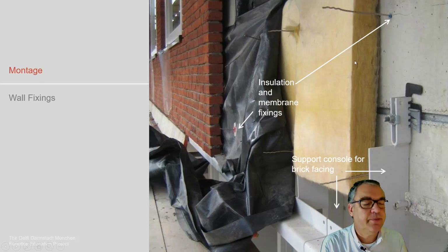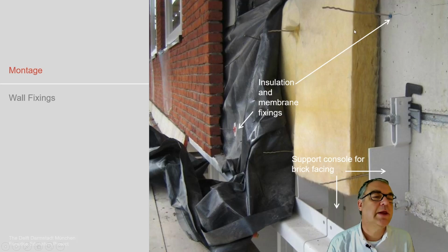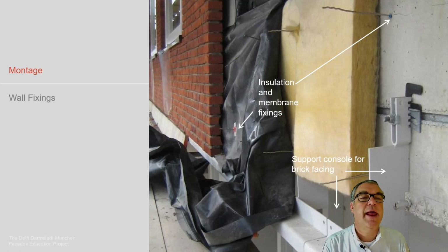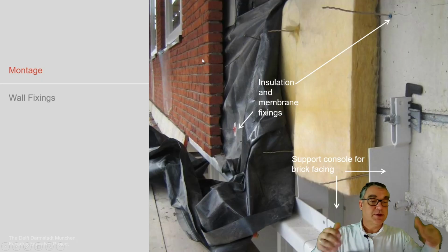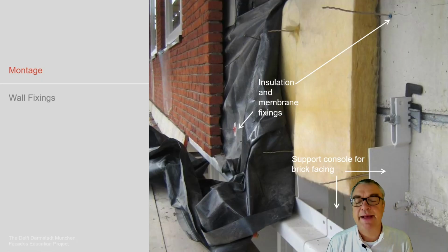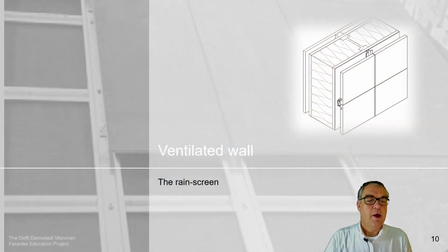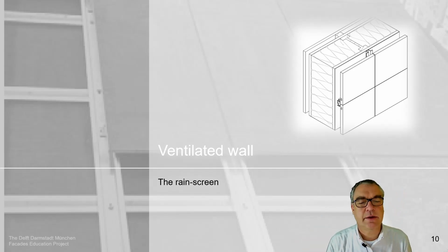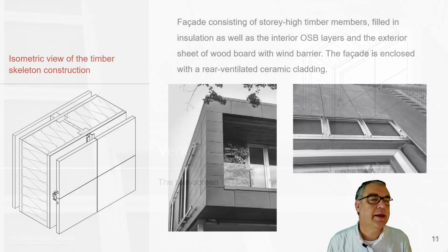We see the insulation, we see the fixing devices, the rods brought into the concrete directly, keeping the insulation in position, penetrating the sealant from the window for the drainage for the window, and then keeping the outer cladding of the masonry structure in position by being mortared into it as a system.